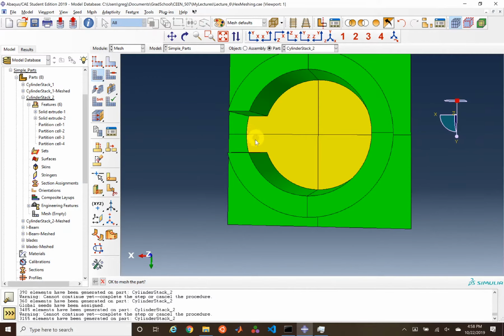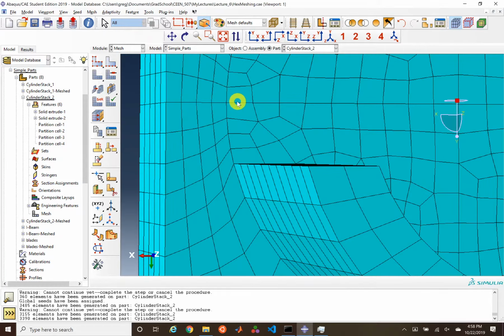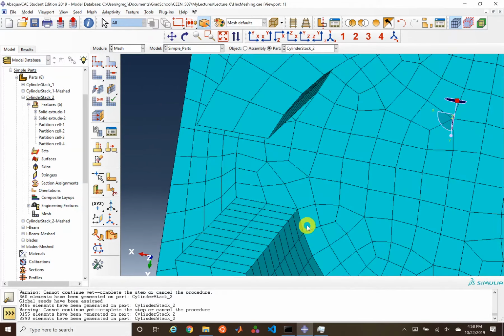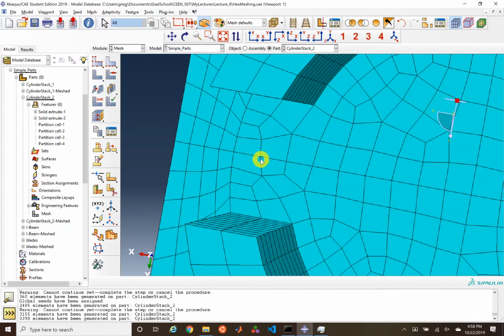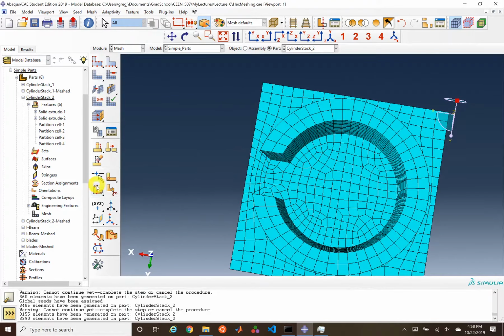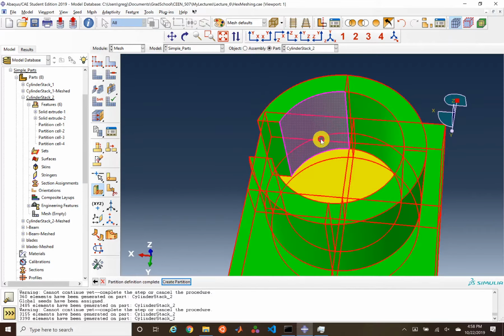If we mesh at this point, we'll see that they do in fact walk all the way across. But still, this node on the inside walks into the middle here, and there's just not as clear a path for it. So this is why we're going to do another partition of the whole geometry with the interfaces.